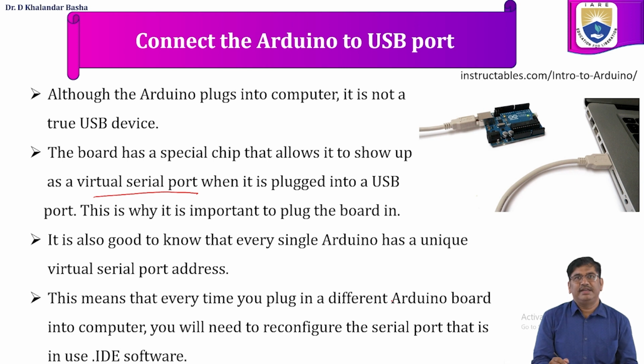This is why it is important to plug the board in. It is also good to know that every single Arduino has a unique virtual serial port address. This means that every time we plug a different Arduino board into the laptop or desktop computer, we will need to reconfigure the serial port used in the IDE software.